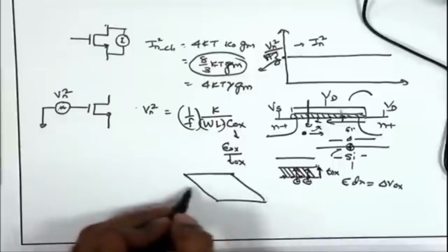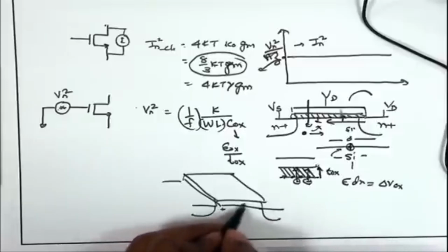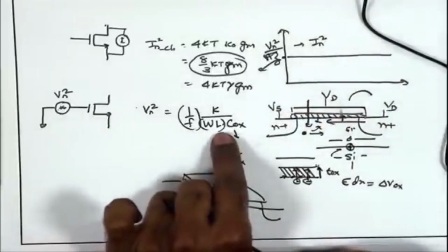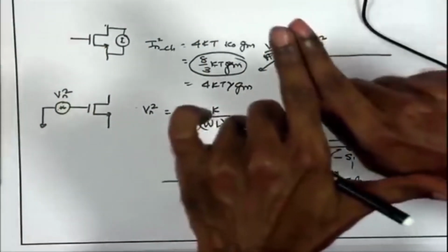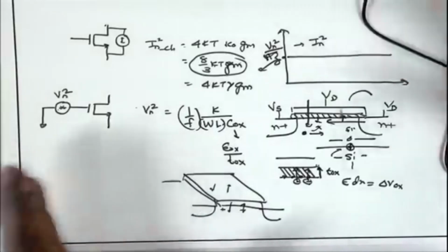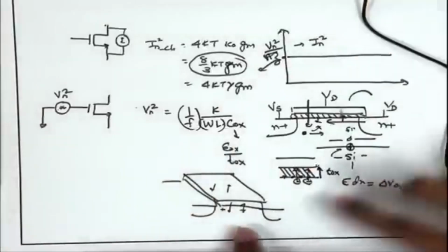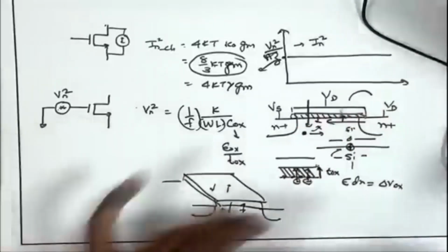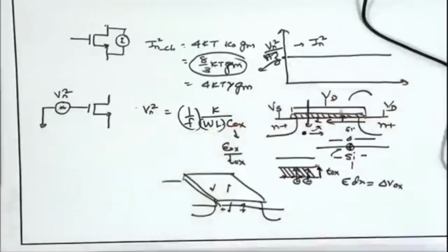because in this entire gate area you are having some trapping detrapping going on. So, larger is the area across which you are integrating, smaller is the mean value. So, just like in case of the random signal, we integrated over a long duration, and then those plus minus 1 will tend to 0 if I sum it up for a long time. Just like flipping a coin, if you are flipping it up or down, if you do it for a large number of tries, the mean value will be 50% up, 50% down. Likewise, here if I assume that there is trapping detrapping going on, if you sum it up over a large area, the mean value tends to 0, because it is plus minus, same phenomena. Rather than averaging in time domain, we are averaging over area, and therefore, we have WL coming into picture.